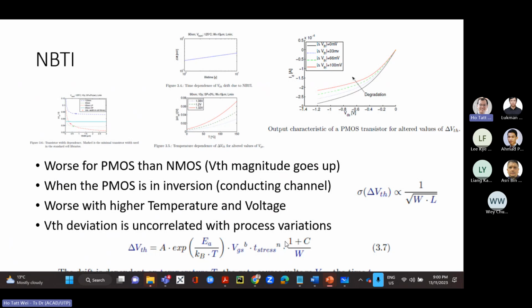And I also may want to ask you to evaluate this comparing different circuits, let's say different transistors. So I have a larger transistor, smaller transistor, different levels of stress duration, different VGS. Would you be able to tell me which one the BTI is worse by maybe a factor of 10, a factor of 100, or how much worse is it? That kind of thing, right? So these types of equations are useful for those kinds of comparative analysis as well.